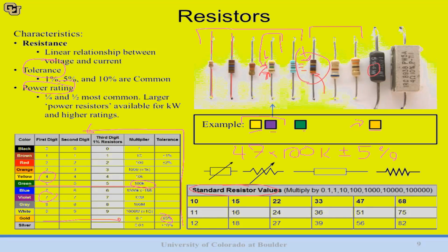So if you wanted to use, for example, a 30 ohm resistor, you'd either have to use a 33 or a 27 ohm. And these are all multiplied by 0.1, 1, 10, 100. So if you wanted a 500 ohm resistor, you could use 510 or 470 ohm. You're not going to get 500. So just be aware of that and pay attention to tolerances. That'll matter when you're building some timing circuits.